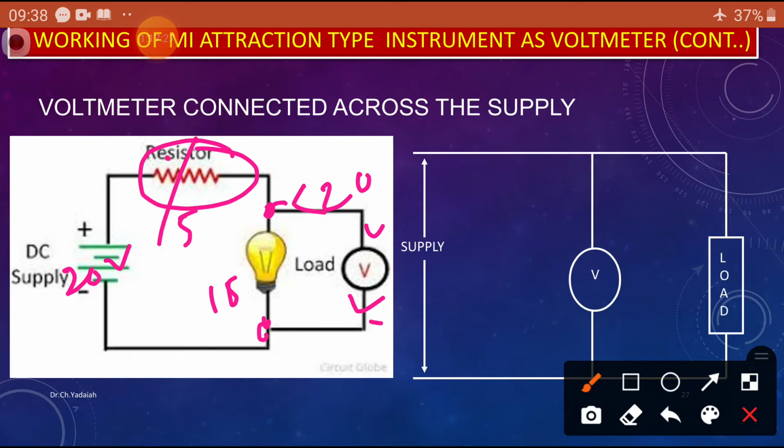This is a variac. By changing the variac, we get different voltages across the bulb, and then the intensity of the bulb also changes. Just like if, instead of a bulb, you connect a ceiling fan with a regulator. By changing the knob positions 1, 2, 3, 4, 5, we get different speeds of the fan. So at step 1, if the fan is running at low speed, what is the voltage across the fan? I find it with the help of the voltmeter connected across the two terminals.